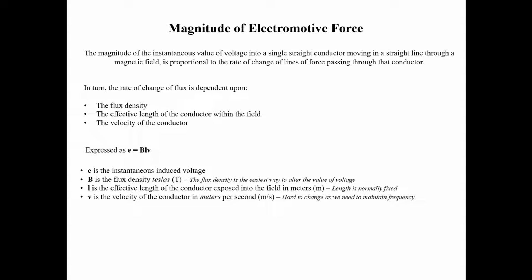An electromagnet is basically when you have wires wrapped around a core that creates a magnet depending on the amount of current that goes through. So if we can adjust the current, we can affect the amount of field intensity. More current, higher magnetic intensity. Less current, lower magnetic intensity or flux density. So that's how we can change the amount of magnetic lines of flux in this machine, by changing the current going through the field windings. The field windings create a magnet, and we can change the intensity of that magnet by changing the amount of current through it. So if we put a field rheostat or a resistor in series with the field winding, we can affect the amount of current that's going through there.